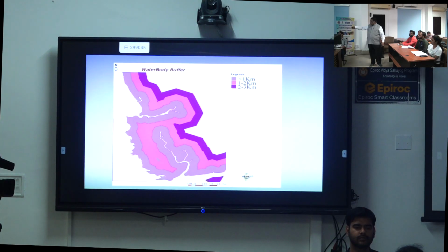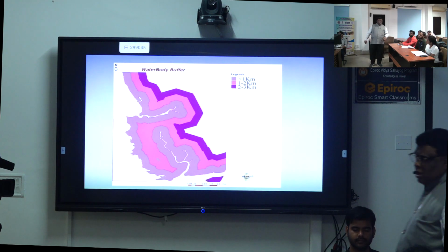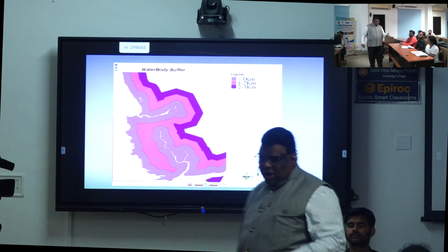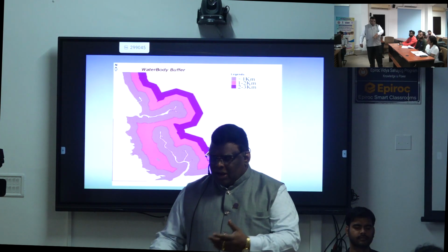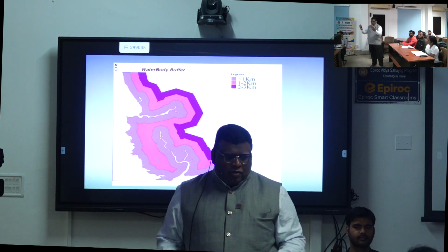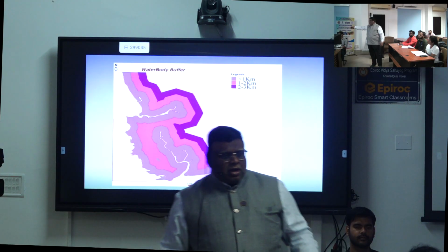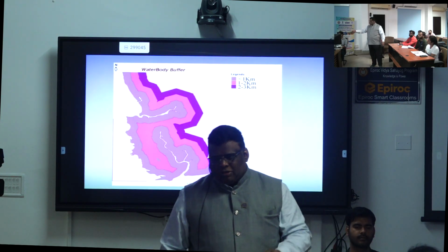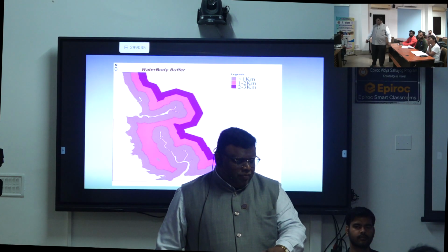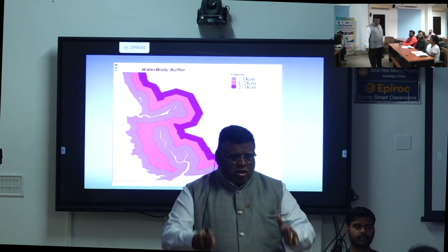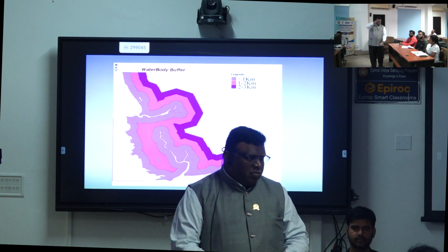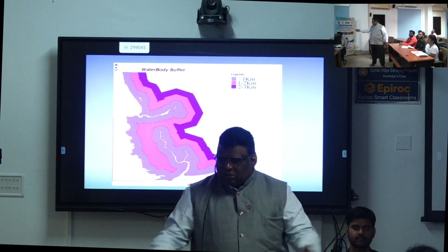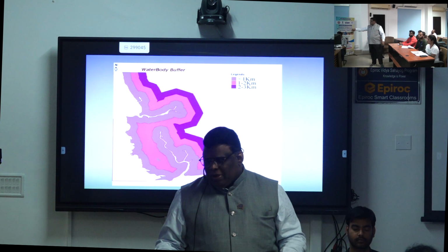This is one of the things, buffer, I am telling you. Whenever a river is there, near the river you should not go for any construction. Nowadays the Yamuna action plan and Ganga action plan are coming up for the rivers. Why is flooding occurring? Insufficient carrying capacity. The river is there, and you are constructing structures very nearby. Whenever heavy rainfall occurs, flood will come, and then there is no way, so inundation is going to happen.